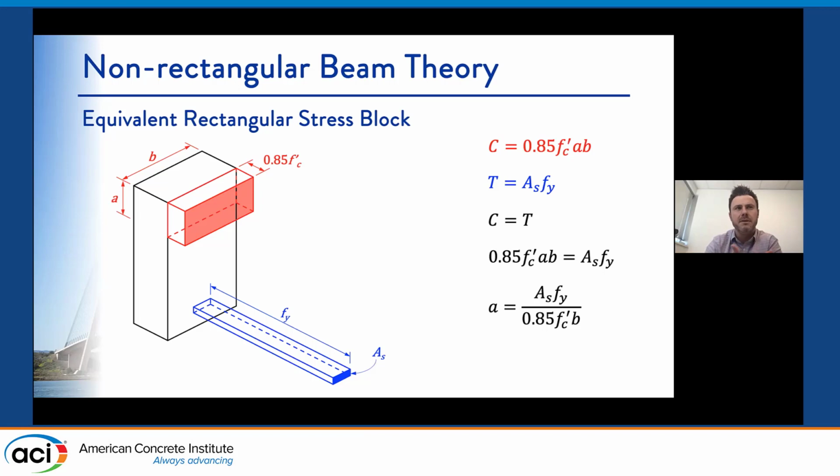And so the way that I do this is I visualize things. You can kind of think about this as the styrofoam blocks that Anahid had. It's just a virtual version of that. And for the rebar, instead of drawing the circles, I just lump it together as one big rectangle. And so looking at this, if we go through that same process, it's a way to visualize the equivalent rectangular stress block, right? So we're taking the compressive force as 0.85 f'c a b. We're taking the tensile force as As fy, assuming the steel yields. We set them equal to each other, and our only unknown in that equation is going to be a.